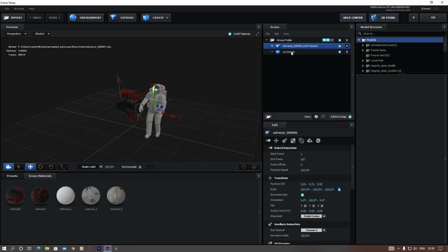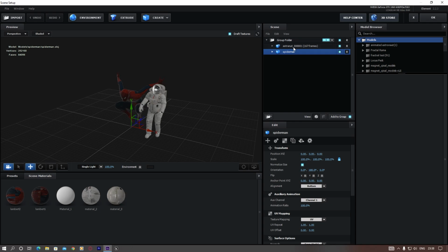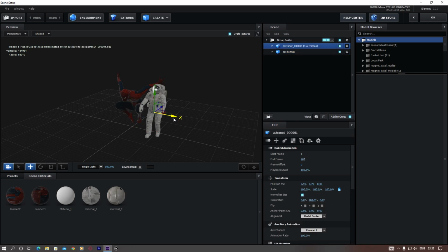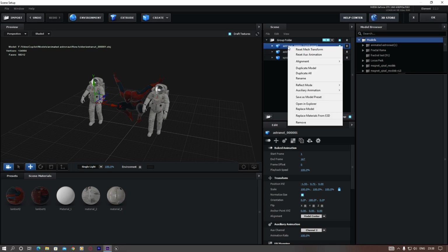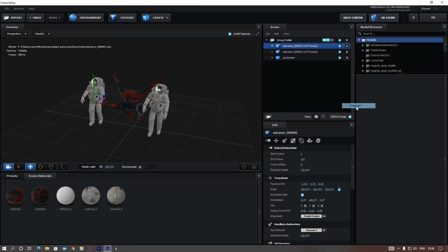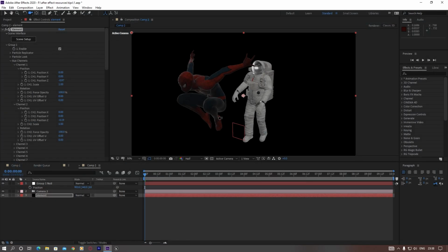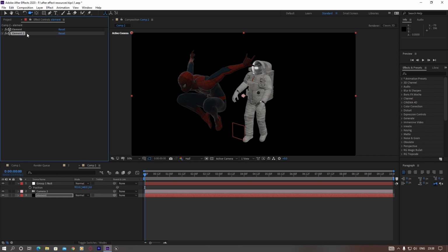let's see, we duplicate this astronaut model here. Just press Alt and move any gizmo here. You can duplicate this and place it here. Okay, and also we place this in auxiliary channel number 3, so we can animate it individually, and then hit OK, and you will see that there is no other astronaut model. It's because this second element layer hides this first element effect.